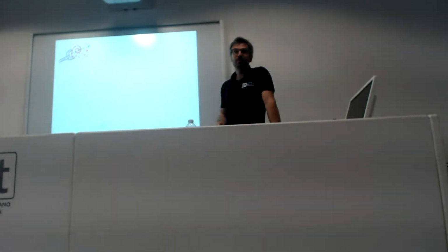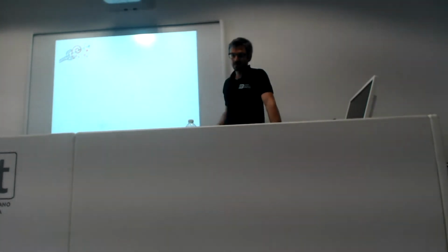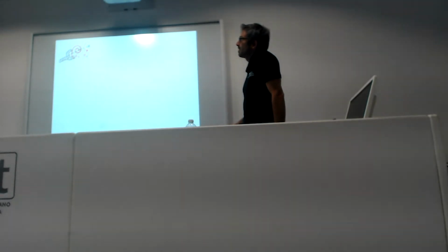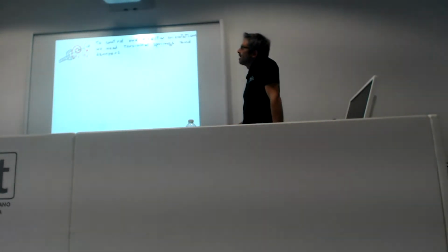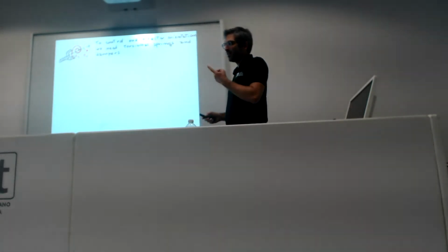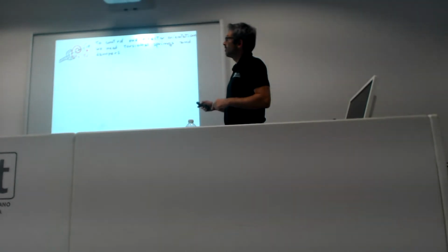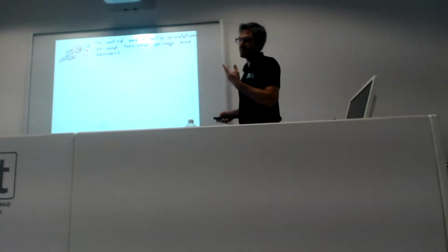Starting from whatever we just said on operational space control, instead of a virtual force, in the case of orientation we can implement a virtual moment, with torsional springs and dampers. In this case, it's a torsional spring around Z, and getting far from the desired orientation will result in a returning moment that tries to attract toward the desired orientation.